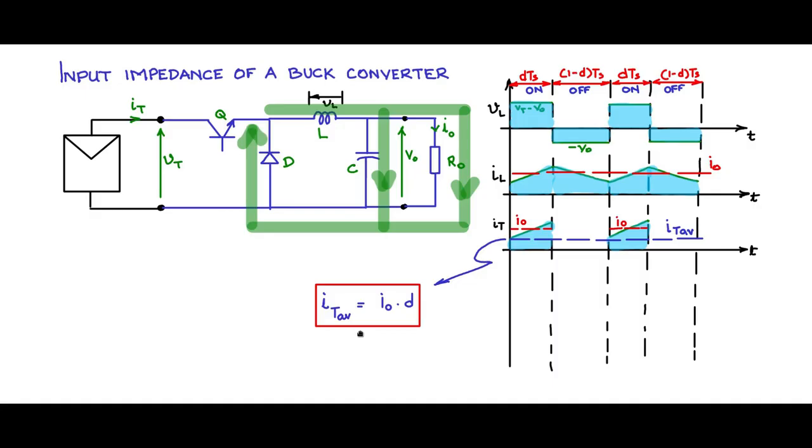In order to make buck converter operation for maximum power point tracking meaningful, we need to have the terminal current flowing out of the PV module as continuous, so that the peak power point can be tracked at every instant of time. Which means that through the terminals we would like to have IT average amount of current flowing continuously from the PV module. How do we do that?